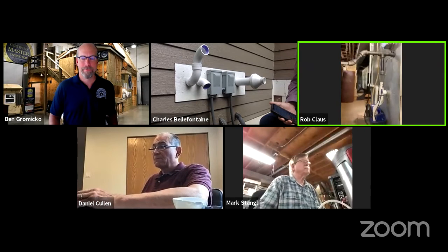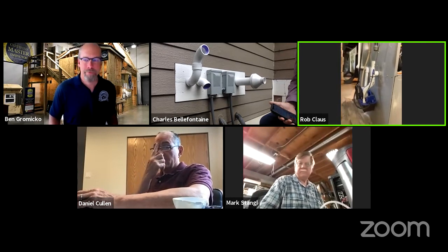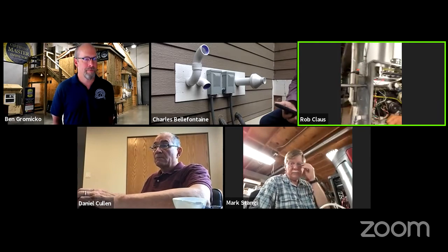Now, you asked Dan earlier about a condensation pump. There's our pump. Excuse me. It's a nice, simple condensation pump. It's hooked up to the electric of the system, and it's there by design because we do not have a floor drain anywhere near this furnace. It catches the condensation of the air conditioner, and it catches the condensation of the furnace. And so we'll look for the operation of that.